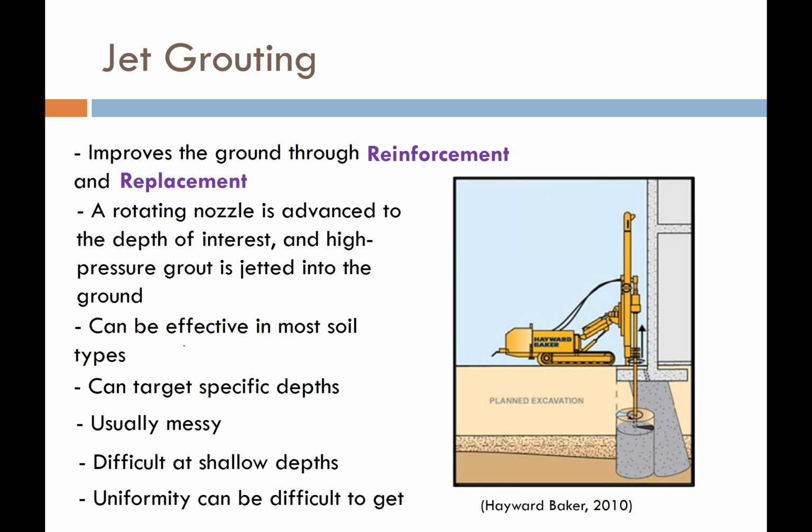So, I mean, this can be effective in most soil types, fine-grained and coarse-grained. We can target specific depths. We can go in at angles. One of the cool things is we can drill through existing foundations and then go right beneath the foundations with it. Because we're not really pumping anything in or making big gloopy balls, we have an easier time with heave.